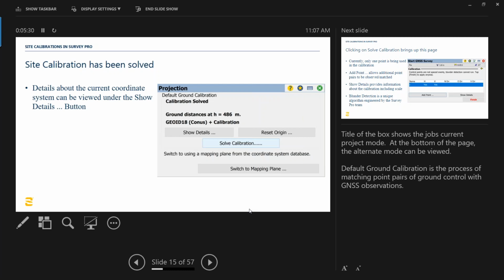Which is not impossible, but the whole point is that you got to think about what you're trying to measure. You're trying to measure a tilted surface that is tilted no more than 60 seconds, and typically no more than 8 seconds. So you're trying to measure a surface tilted at 8 seconds, and you're trying to do it with a GPS pole that's measuring 2 to 3 centimeter verticals, right?